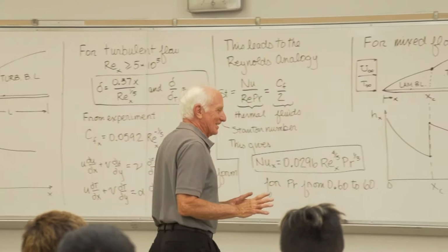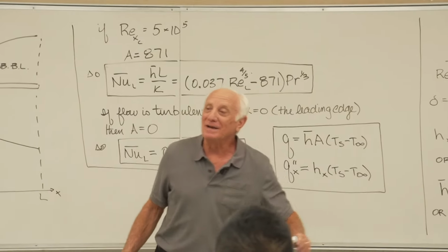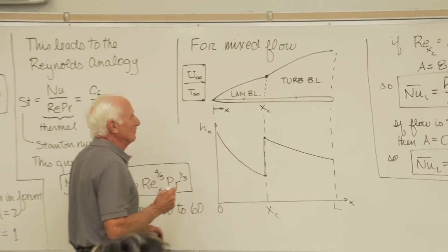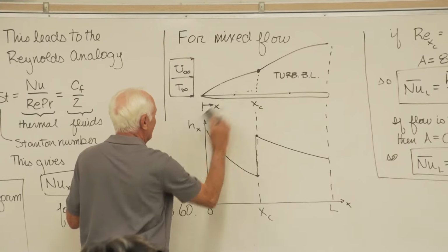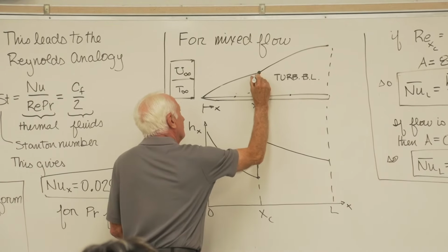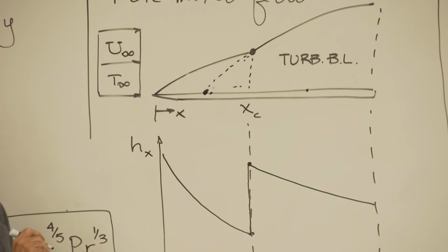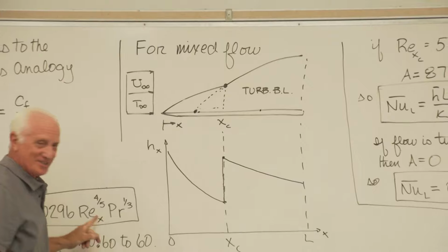Okay, I'll give you a major hint here. That's an approximation, because really, where does that turbulent boundary layer appear to have started? There. What distance should you have put in? This distance in that equation.